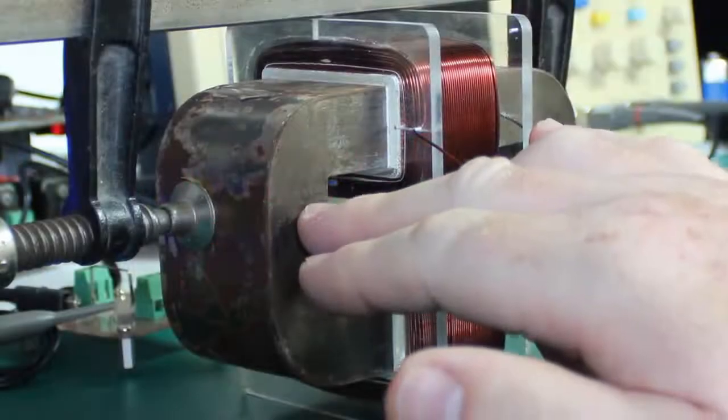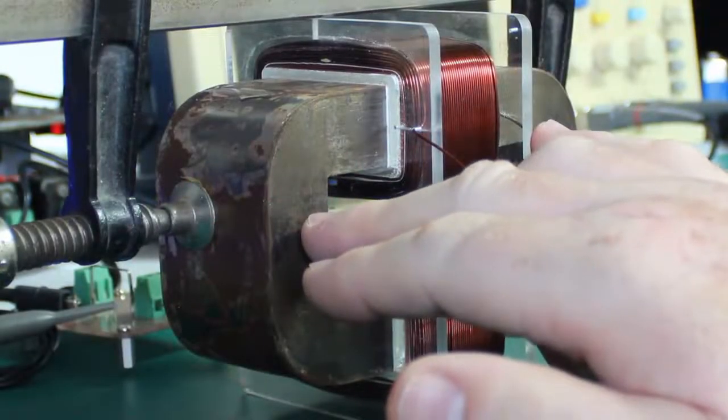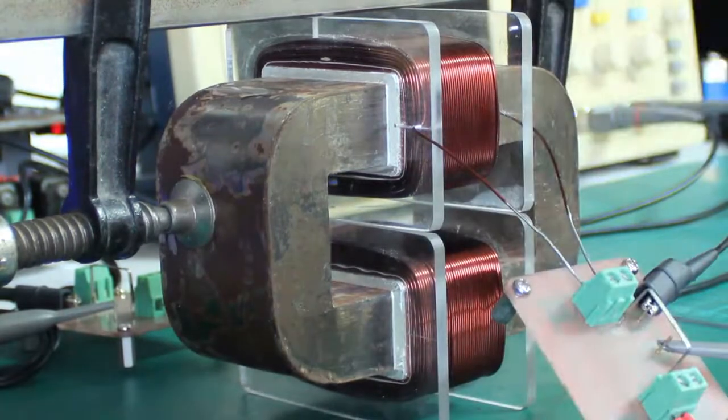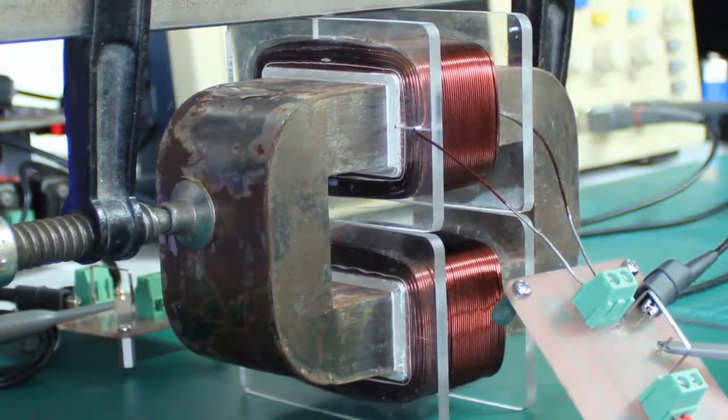Okay, remembering these cores, some of these metglass cores are up to about 600,000 for permeability. So they're very, very permeable cores. The magnetic field is going to go through those well before spilling out to space. However, they do saturate and can saturate. Some of them are about a Tesla, so it has to be a fairly high magnetic field, but they can saturate and do saturate, so you have to be careful.